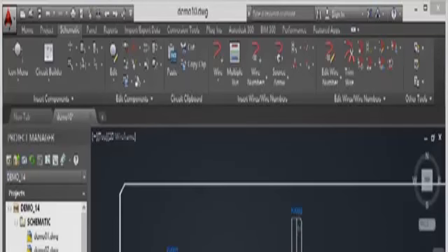So we're staying in drawing Demo 10, and we're still in the Demo 14 project over there on the left in the project manager. There'll always be the occasion where you've got to reverse a connector in your drawing. So let's just zoom out one notch here. You can see that the connectors at the moment have the pins on the right hand side of the connector. It's very, very easy to reverse a connector. Two ways of doing it. You've got the ribbon and the mouse. Let's look at the ribbon method first.